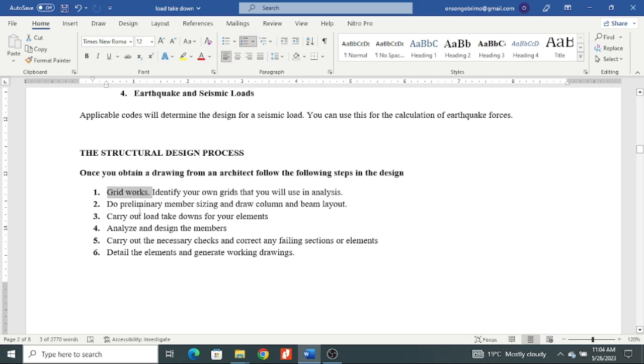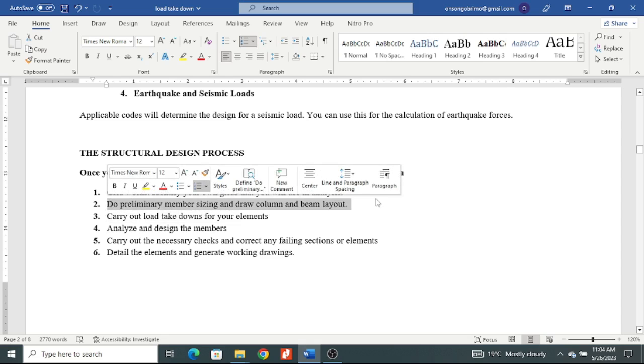After determination of this, you should also use your experience and a few checks here and there that enable you to do the sizes of beams, columns, foundations and slabs and all that. Sometimes, if you're a young engineer who has not been experienced in carrying out design, preliminary design becomes a challenge, because you don't know the depth of the beam you're going to use for such a span.